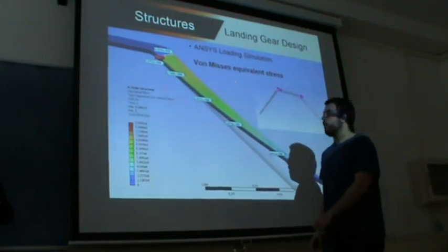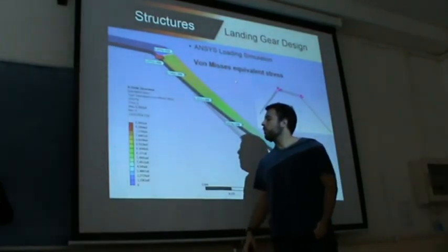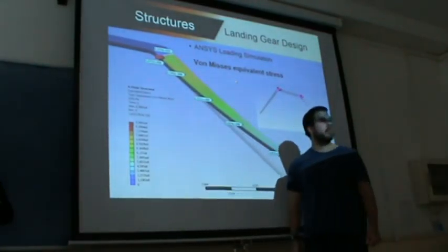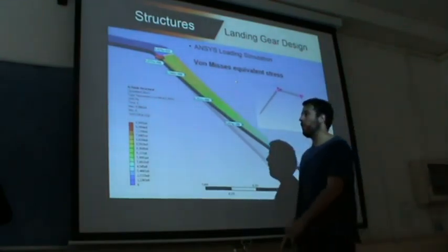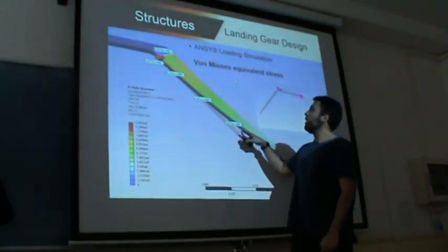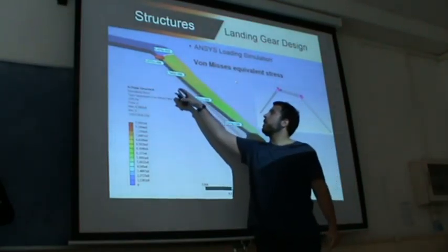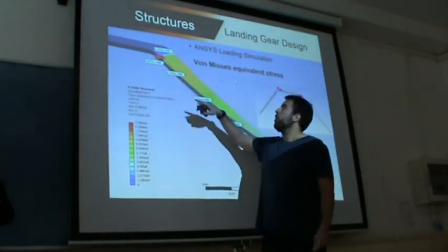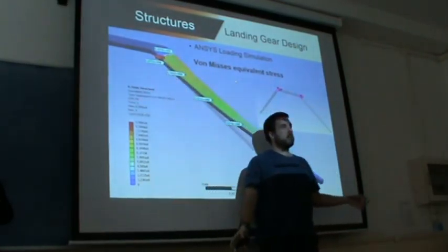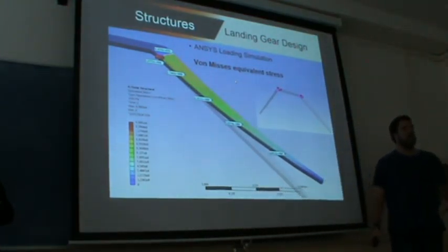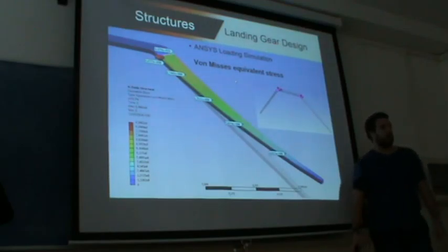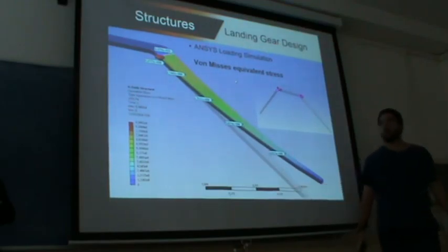I've not written it here, but the admissible stress is 0.8. And we can find that the stress doesn't surpass this limit, except for one point that we believe is a mesh problem, because the mesh was about 2 millimeters. But we think that it's not enough to calculate the complete stress.